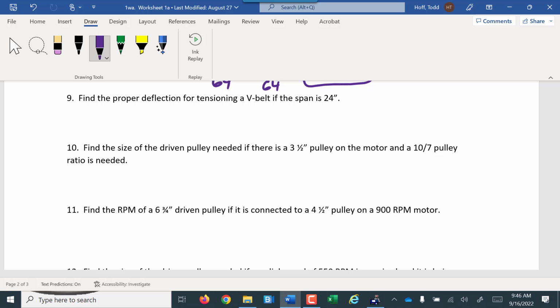Have they given you guys an exact amount of force for that? No? Yeah. Have they? We have some stuff. Yeah, we have like a weird tension meter. We actually go underneath the belt. You hang on it? Yep, you hang on it. Belt stops moving. Okay. I've never seen it in a book anywhere that says you apply so many pounds of force to it. You actually pull up on it, and it has a gauge where the spring pulls into that gauge, so you know you got the right tension. Style weight scale. Yep. It's called a go no-go gauge. So when it's in the range, you've got your acceptable. Pretty much. I think they asked for like 8 millimeters. Okay. Cool.